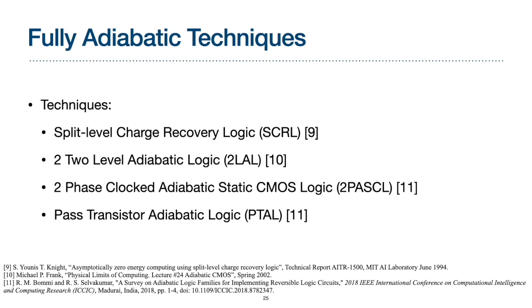Here we have listed alternatively a few of the most popular fully adiabatic techniques that I've seen. A couple of these techniques we discussed before. This includes split-level charge recovery logic, or SCRL, and two-level adiabatic logic, or 2LAL. Additionally, what we haven't discussed before are other techniques such as two-phased clocked adiabatic static CMOS logic, or 2PAS-CL, and pass transistor adiabatic logic, PTAL.